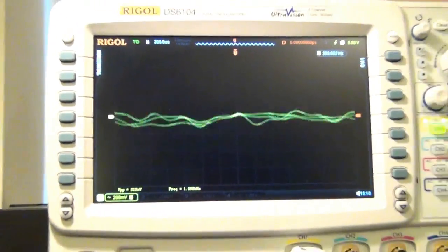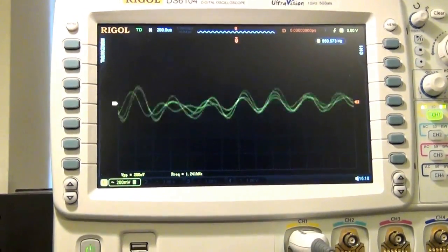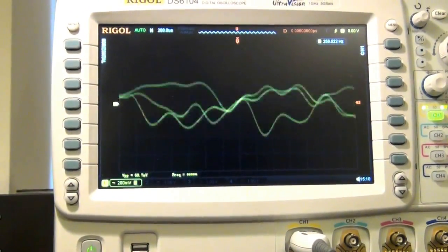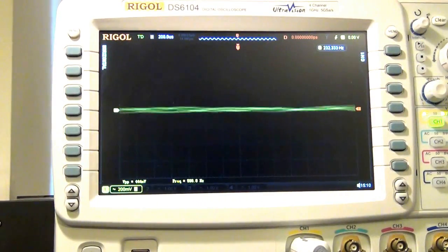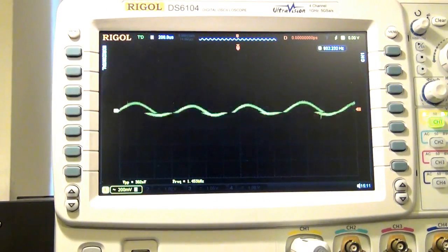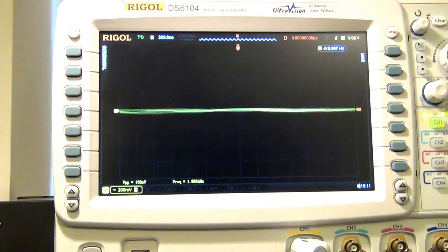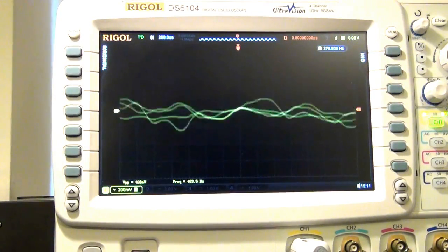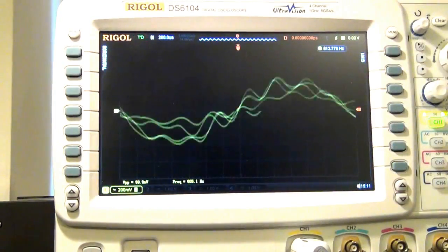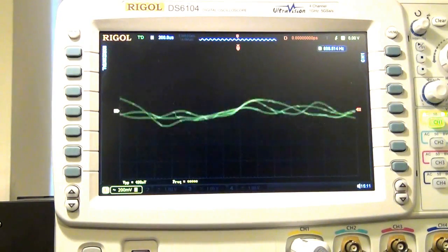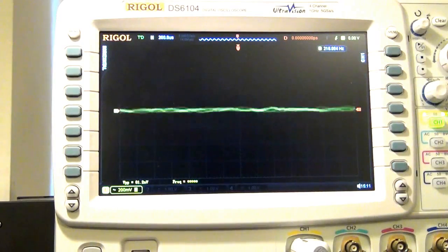Here you go. This is the output of the oscilloscope. You can see as I'm speaking, it's picking up the audio signal and it's amplifying it. You can see the time waveform there. So if I whistle, you can see that it is in fact doing a very good job at amplifying it. This is on a 200 millivolt peak-to-peak scale, and I am easily getting signals that are almost 1 volt peak-to-peak from this amplifier chain.